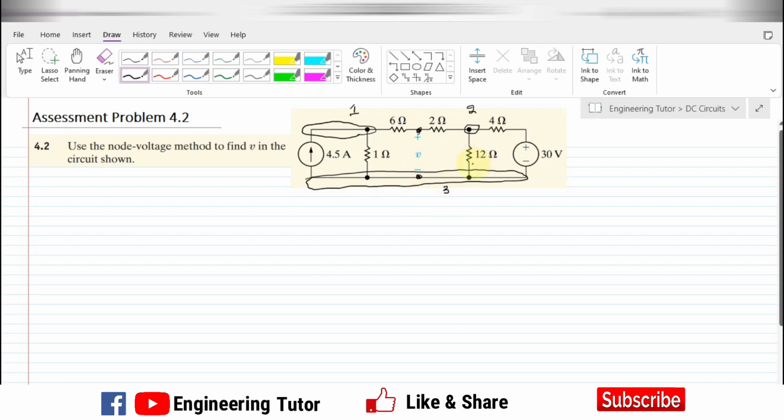In the first step, when we have identified all the nodes available in this circuit, we have to make the equivalent circuit. So let me make the equivalent circuit. This one and this one, these are our two nodes. Let me call the voltage at node 1 as V1, the voltage at node 2 as V2. This is the resistor of value 2 ohm. This is 6 ohm, and this is 2 ohm.